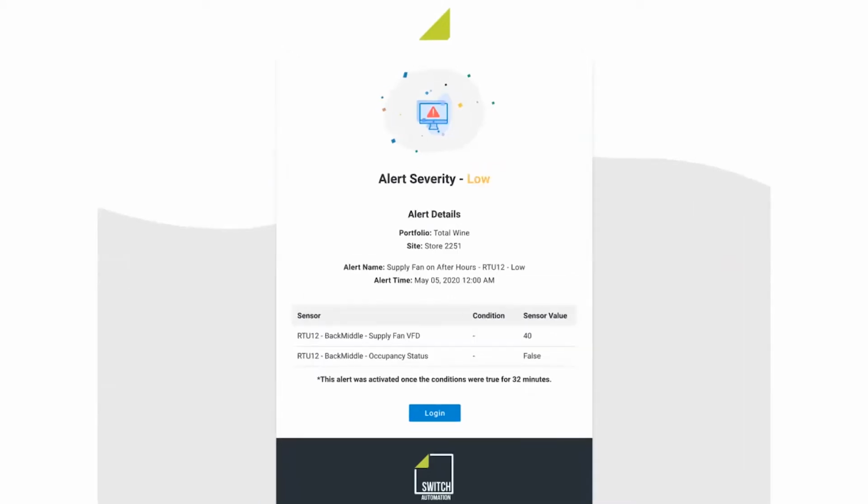You can also set up alerts to notify you when equipment may continue to run even though your occupancy sensors and data show that the space is unoccupied. This allows for proactive action to investigate before waiting for someone to personally notice and wasting energy in the process.